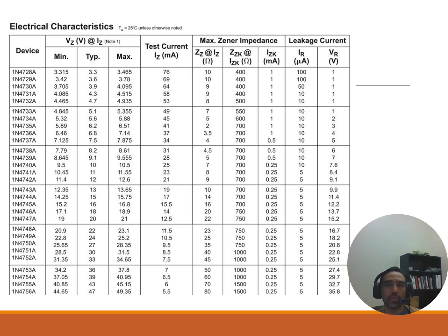Why is it important to look at these data sheets? Knowing what the Zener voltage of your component is, that's the main job of the Zener voltage. That's going to let you know what voltage you're trying to regulate, so it'll tell you what voltage your circuit needs to be handling. The test current just ensures that the diode maintains voltage under typical operating conditions.